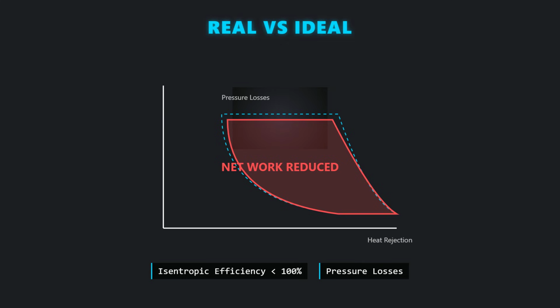the atmospheric pressure. Real gas turbine cycles inevitably deviate from the ideal Brayton cycle due to inherent irreversibilities, primarily caused by aerodynamic friction and unavoidable heat transfer losses. Compression and expansion processes are not perfectly isentropic, resulting in entropy generation and a measurable reduction in net work output. These losses are quantified using component isentropic efficiencies.